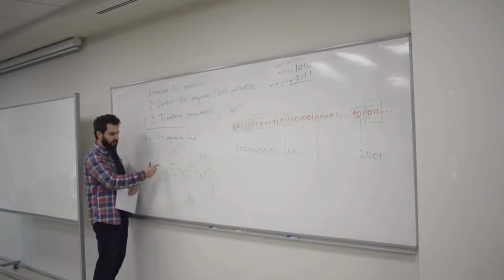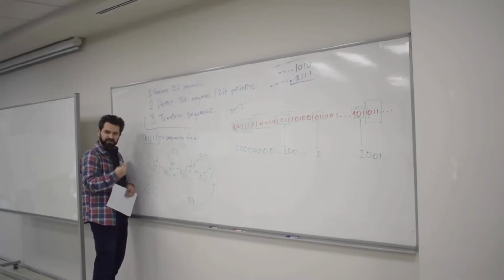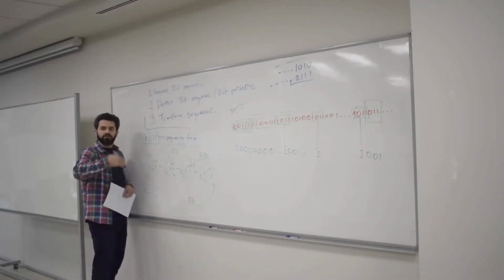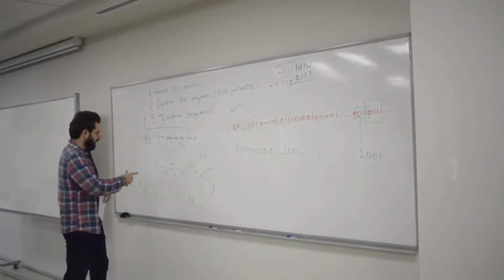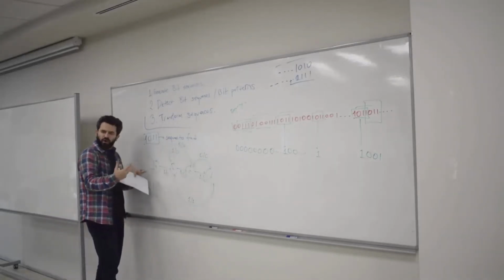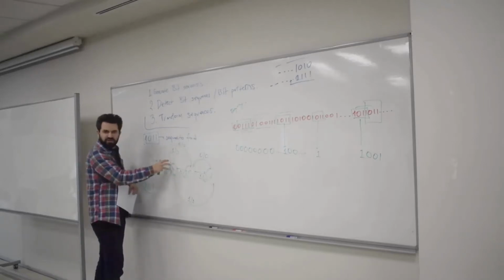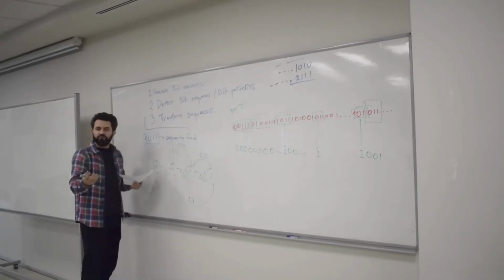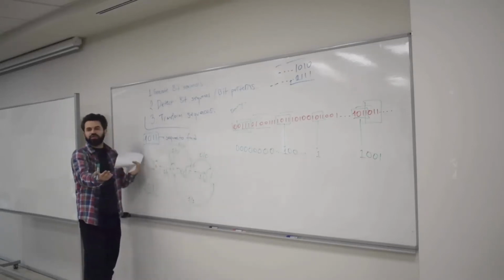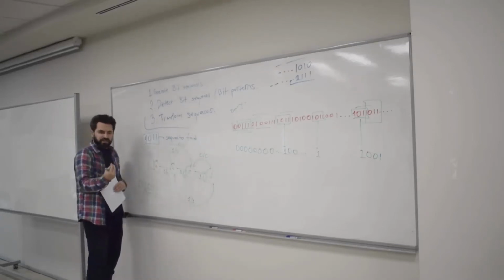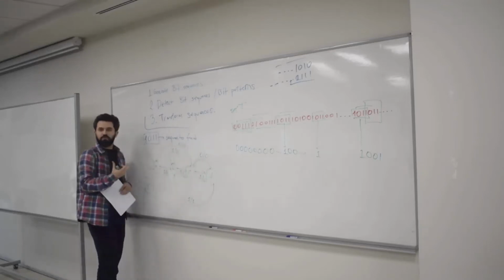What you're seeing is that these transitions can only happen at specific time instances, which we call the clock signal. The clock transitions: when you have a rising edge or a falling edge, you have those transitions. There's no input-output relationship here because there's nothing being processed. It's not like a flip-flop processing something. This is a logical diagram. It's all logical.